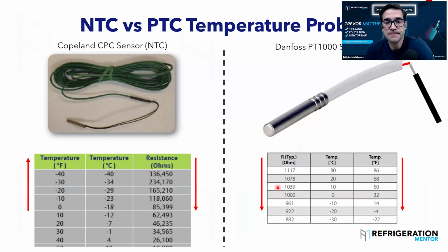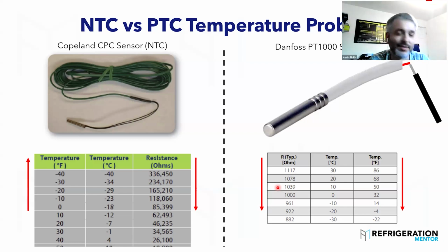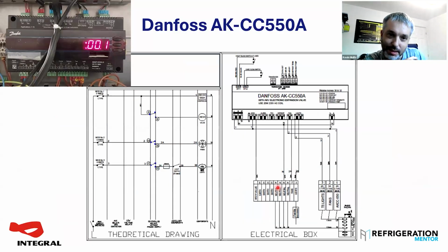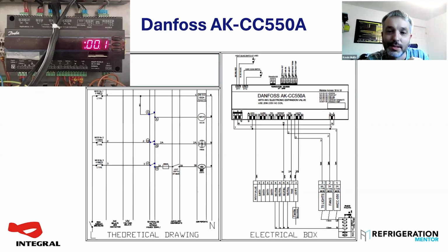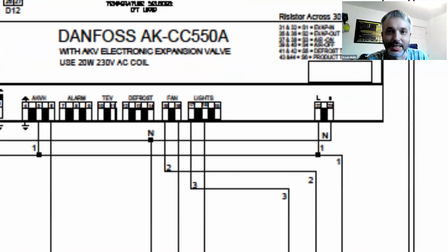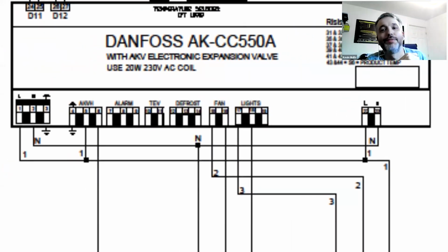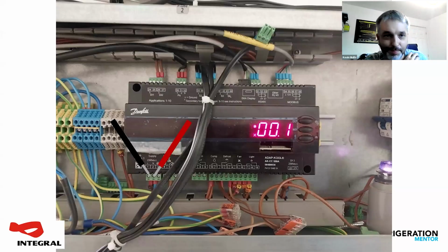Yeah, that point. I will say the 550 is bulletproof, so you'd have to go some to break it. But one thing we did speak about last night, you could actually see it on the wiring diagram for the 550. Your digital inputs 1 and 2 are volt free up on the top left of the controller, but digital input 3 on the bottom right of that drawing is a high voltage input. So that is expecting line voltage to change that status. And if you have been unfortunate enough to put the line voltage one on the volt free one, it's probably not going to be very happy.